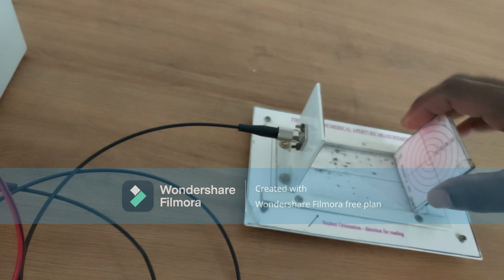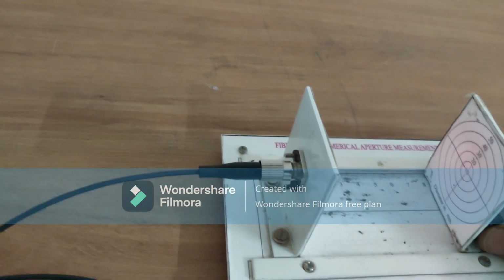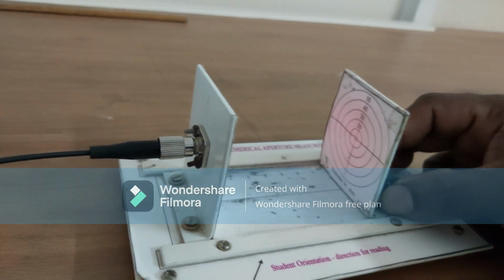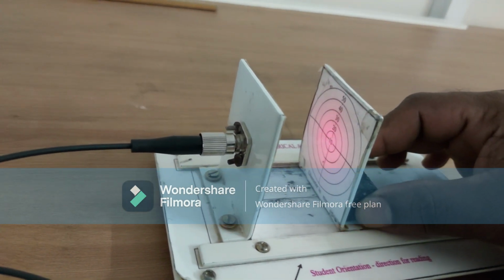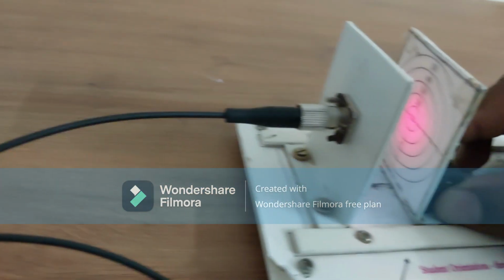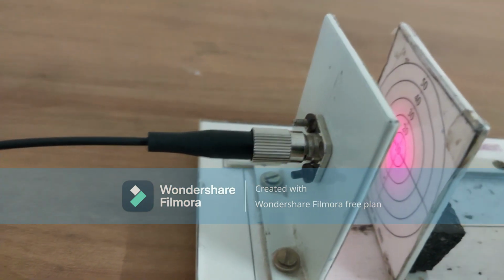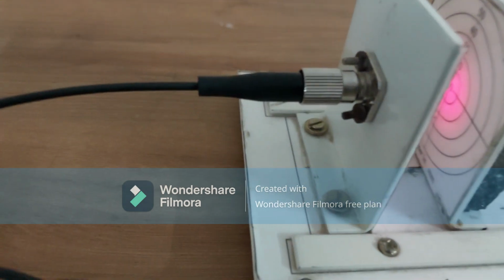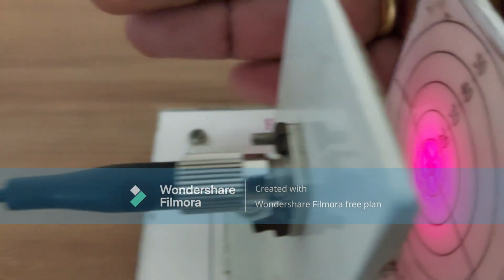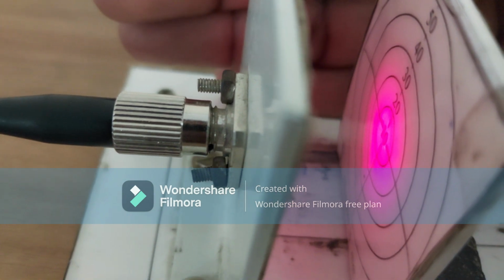Now place the screen on the numerical aperture jig at a particular distance, and now move the screen towards the numerical aperture jig until the complete light is confined to one particular ring. For example, if the light is going to be confined to the 20 millimeters of ring diameter, maximum intensity light is going to be confined to the 20 millimeters of ring diameter.